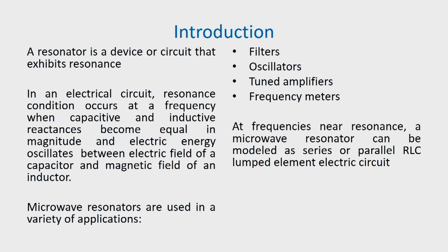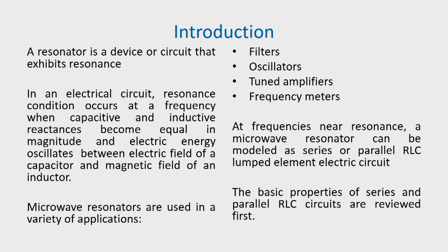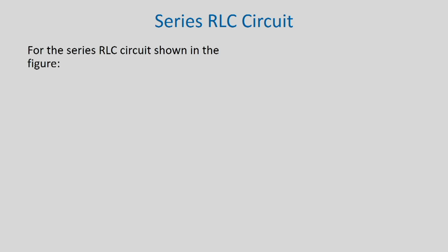Now, at frequencies near resonance, a microwave resonator can be modeled as a series or parallel RLC lumped element circuit. Therefore, the basic properties of series and parallel RLC circuits are reviewed first. So, we consider the series RLC circuit, and for the series RLC circuit shown in the figure,